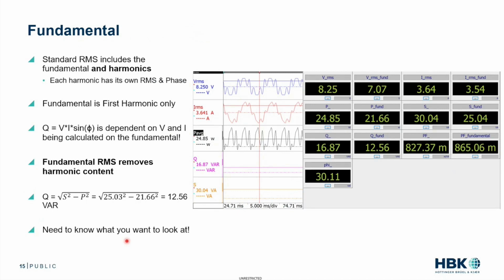Okay. So now let's look at the fundamental, because fundamental is something that's very valuable to engineers. A lot of engineers ask for the fundamental, and we'll touch a little more on that. I introduced it earlier, but let's talk a little more about it. The standard RMS contains the harmonics. Each harmonic has its own RMS and phase. When we refer to the fundamental, we are referring to the first harmonic only.